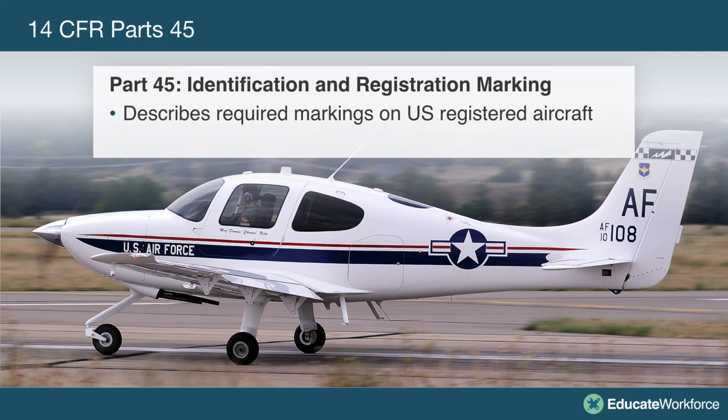Replacement and modification parts which are produced in accordance with manufacturing approval, or PMA, parts manufacturer approval, must have the following information permanently and legibly marked. First off, we have to have FAA PMA. Then we have to have the name, symbol, or trademark of the holder of the PMA. We have to have the part number. We have to have the name and the model designation for each type certified product on which the part can be installed.